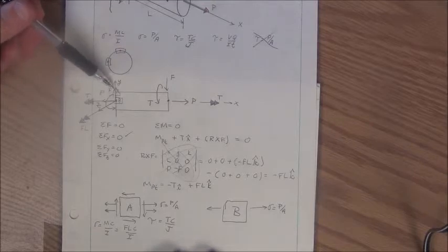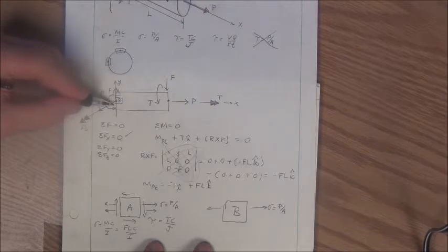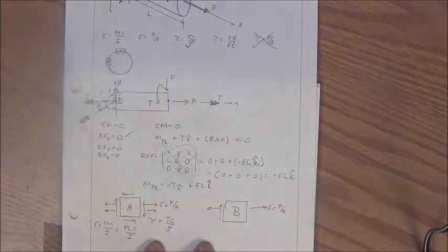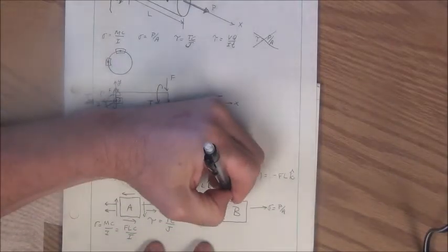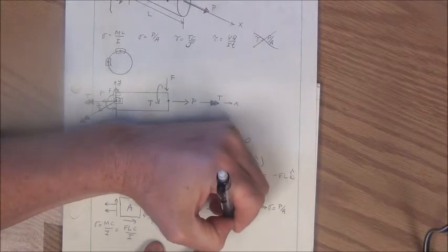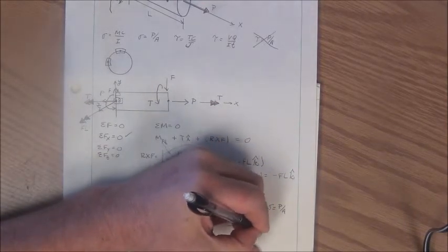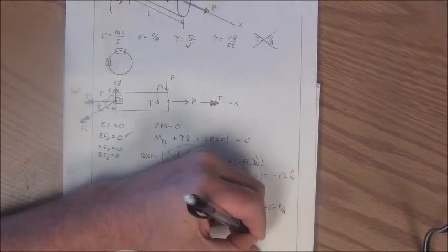And again, it's in tension because P on the cut face is pulling in this direction. The load F in the vertical direction now is parallel to this face here at B. So it's going to act right along that. It's parallel to that face, and that will cause a shear due to bending. So this would be a tau is equal to a VQ over IT.